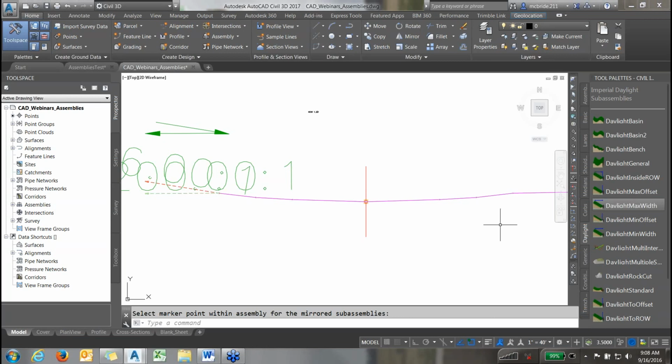Just one comment that it's a 9-point check with the dots outside of the waterway, but yes. Yeah, I think what you're trying to do is make sure you get the elevations within the waterway that we're going to survey close and not approximated by the line. Right. Yep. Yeah, but that's a good point. Technically, it is a 9-point check, 7-point in waterway, then 2 points further outside. That is a good point. We should be reminding people of that. So yes, it is a 9-point check.